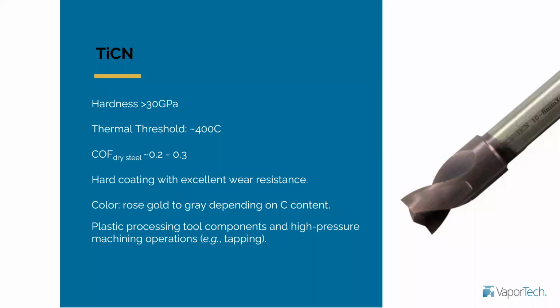It has good applications for a high pressure machining operation. So if you think of titanium nitride, it is used in turning and milling and so on. Titanium carbon nitride can also be good on those, but in a high pressure application, in which high pressure means that you're going to have the contact pressure at the surface of the part be pretty high, which is different from one of the other ones, this coating performs quite well.